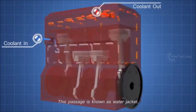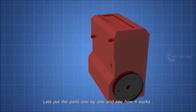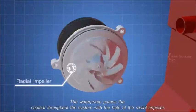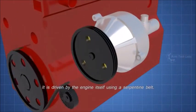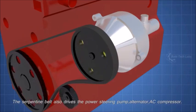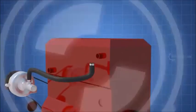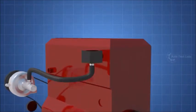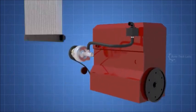Now let's see how these parts work together. The pistons are contained inside the engine block, in which each of them will function. Above the engine block comes the head gasket, which provides sealing between engine block and engine head. It avoids compression leaks and oil or coolant leaks into the cylinders. Above that comes the engine head. The engine has a safe passage through which the coolant can flow without entering into the cylinder or mixing up with the oil. This passage is known as the water jacket.